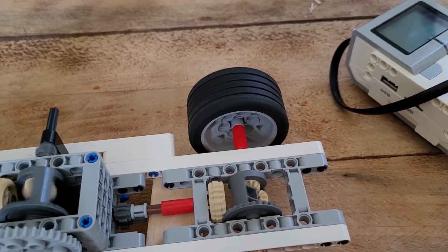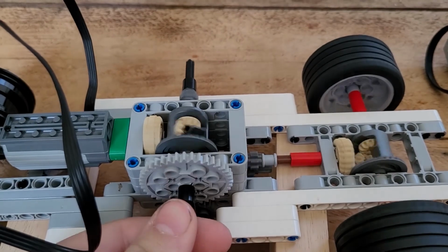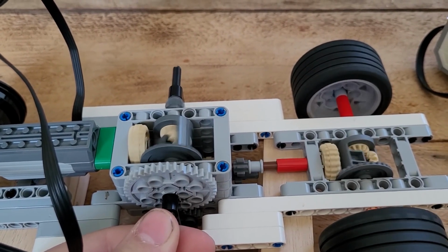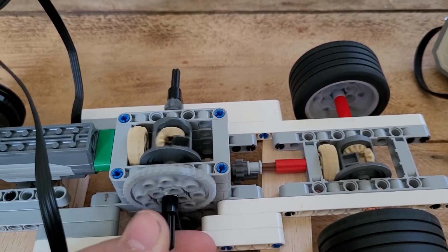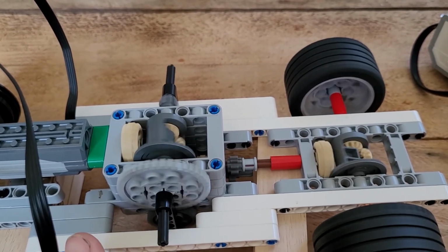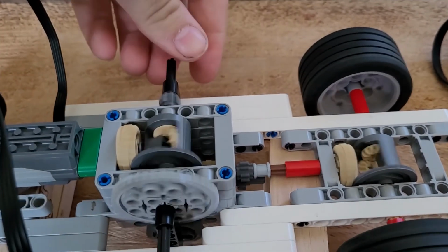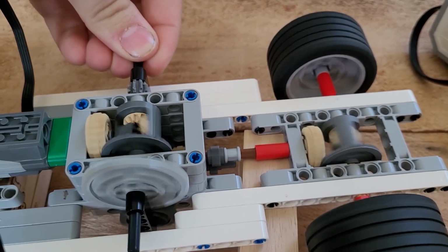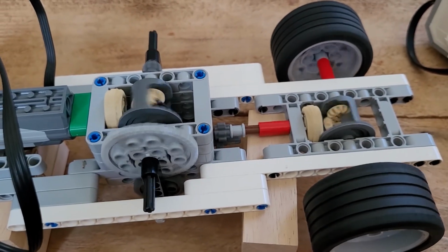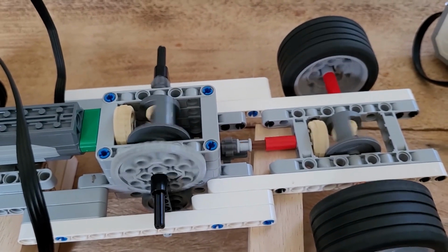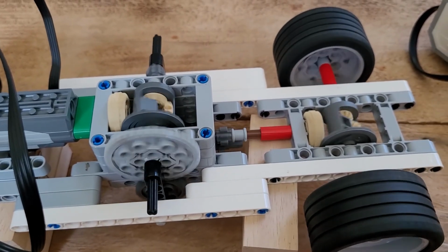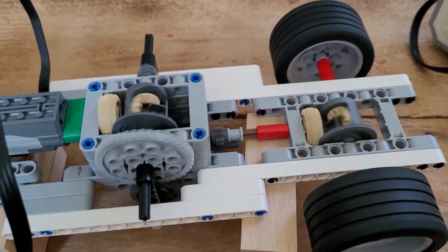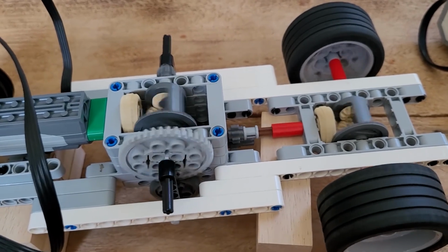Locking in first gear, I'm just doing that to lock in first gear. I lock out the overdrive gear, so the only possible ratio it has to spin on is the equilibrium of first gear. Releasing that is the equilibrium between overdrive and first gear, which gives a second gear, and then locking out first gear gives me only overdrive, so then everything spins at overdrive. And then I'll show you on a series of flat terrain, incline, and downhill how the car will shift between the 3 gears on its own to allow that electric motor to spin at its constant speed.